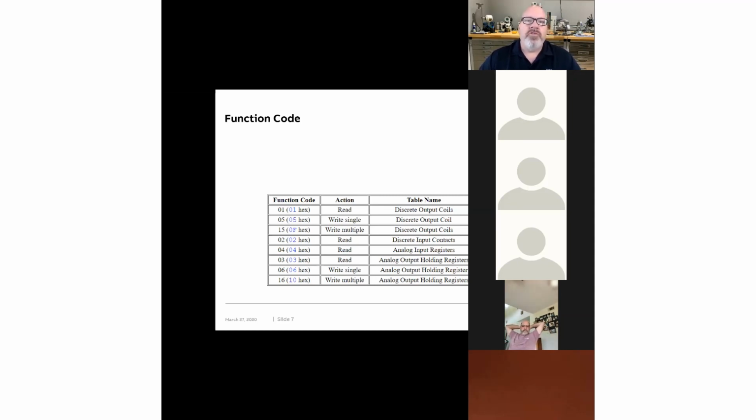Now, a lot of times we can also ask for the whole list, and then on the master side, when we get back 50 registers, I may only need 3, and I'll just parse out or look for those 3 registers in the reply and use that information and discard the rest. It can be more efficient. But it makes a larger response, with more data packed into the response coming back. So in the old days, we really had to worry about the bandwidth. We still do to a certain extent, but how large these messages were and how frequently we were pulling information.